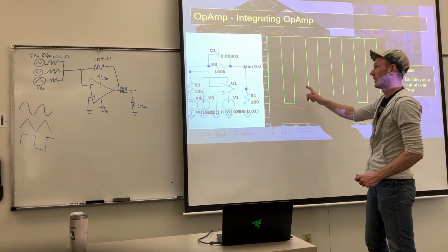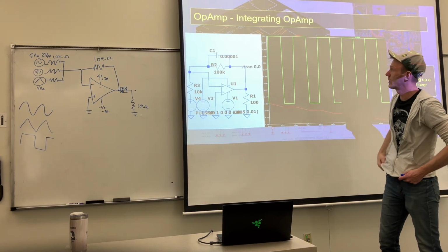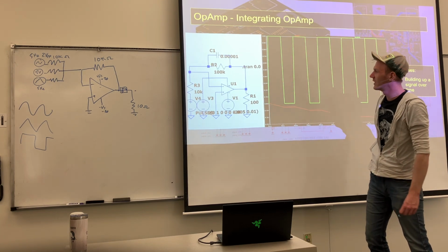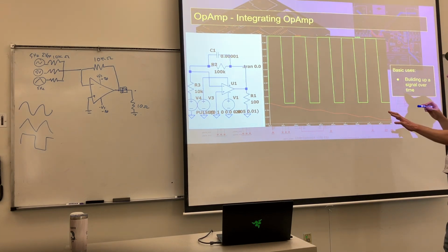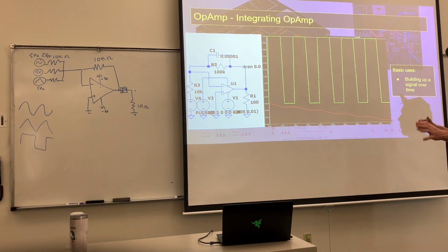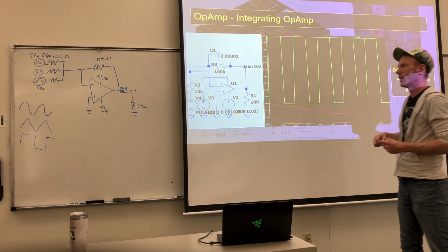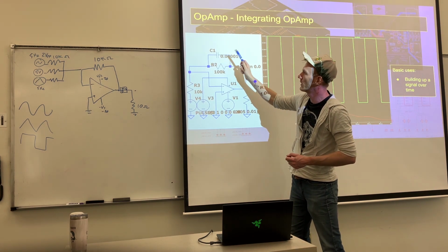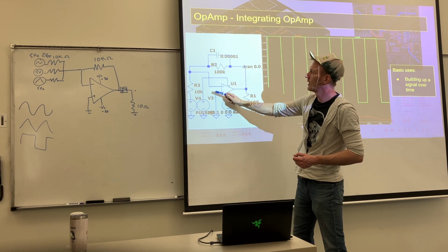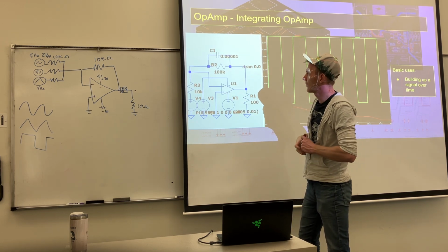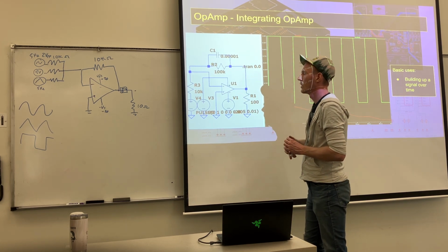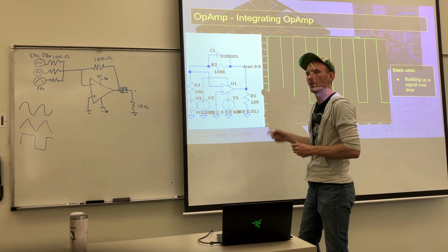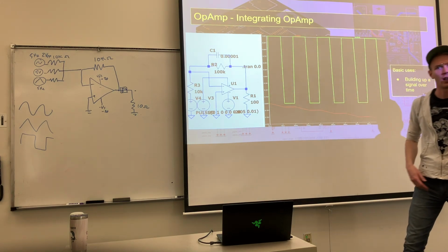This is not using an ideal one, so you can actually see that this is not instantaneous anymore, if you can really pick out the 1 pixel differences every now and then. Again, the normal operation of this inverts it. The thing to notice here is that you have a capacitor in parallel with a resistor connected up to the negative terminal, generally how this works. A differentiating one, I think, has it in series. Yes, has it in series. But you can do differentiation as well.